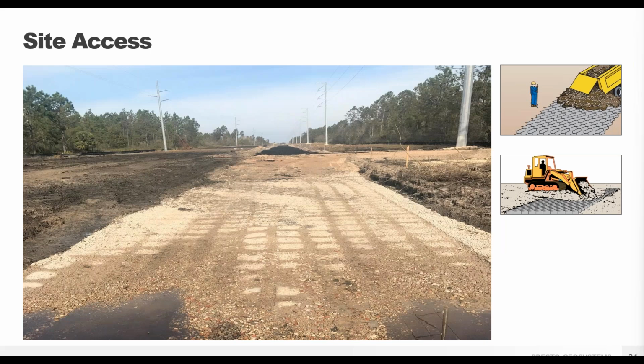Once the panels are filled in, both wheeled and tracked equipment can drive over the systems easily, even when the infill material is sand or other low-quality stone. Again, we see how the GeoWeb panels act as their own access road. Just keep filling up the cells in front of you. No need for additional temporary roadways. This is a great construction time saver and a resource saver.